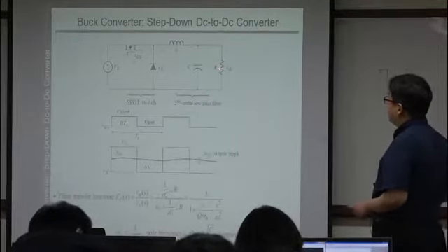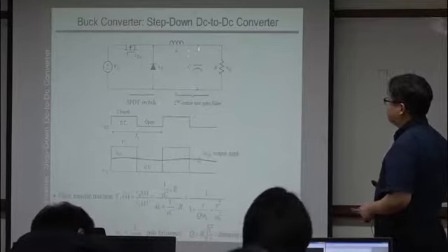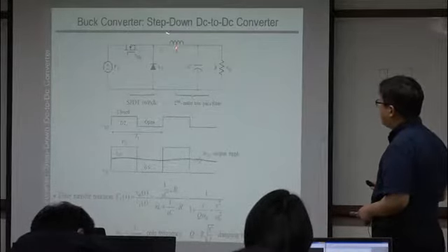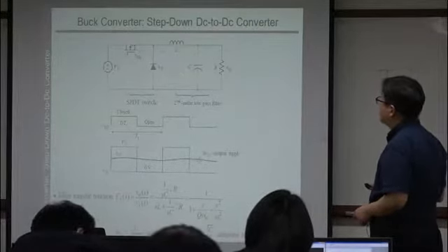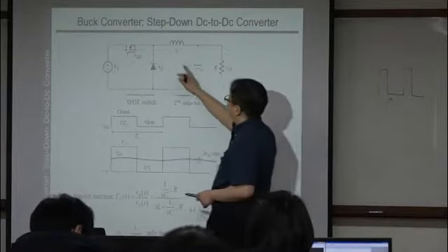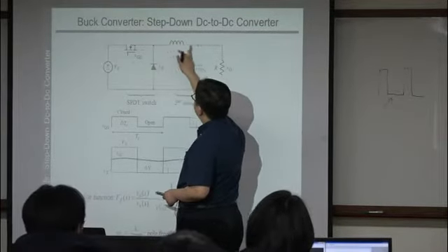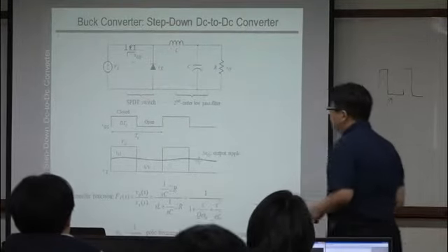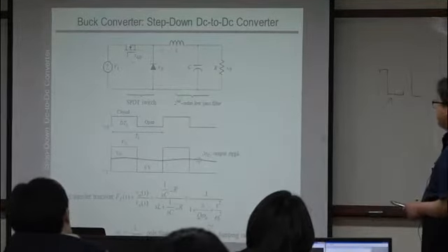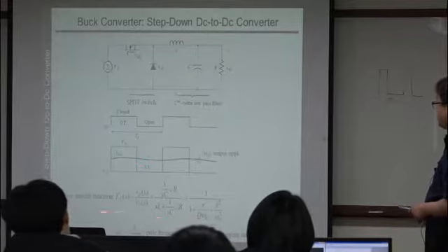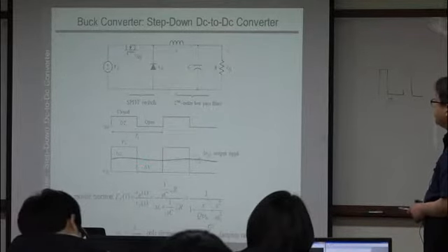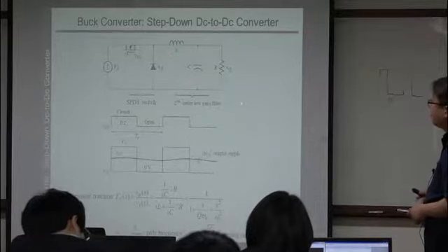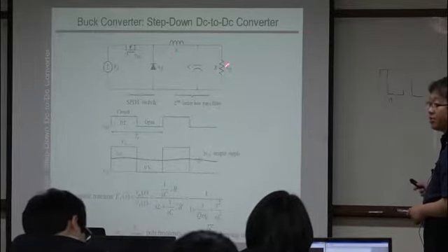And what about the LC filter? Here we just simply model it as ideal L and ideal C. But in fact, you have a parasitic resistance component here. Then let's simply calculate the filter transfer function. Its input is Vx, a switched waveform. And what about the Vo? Vo is a filtered waveform.